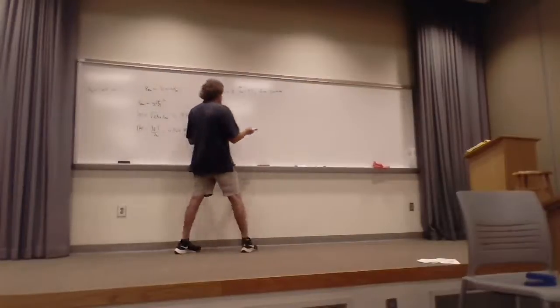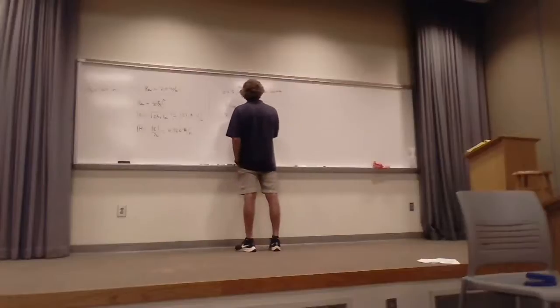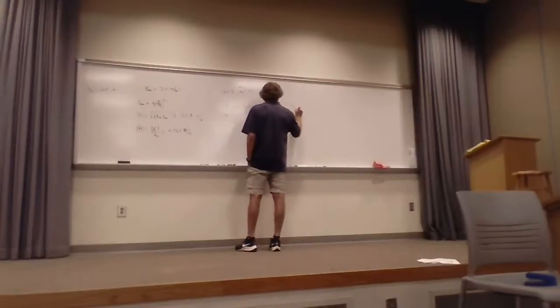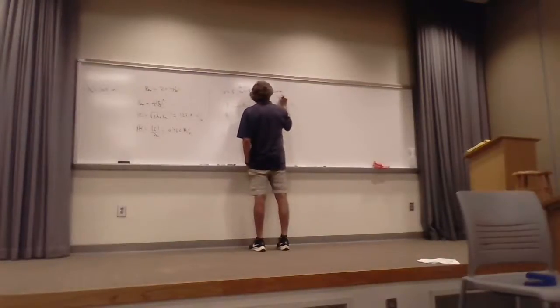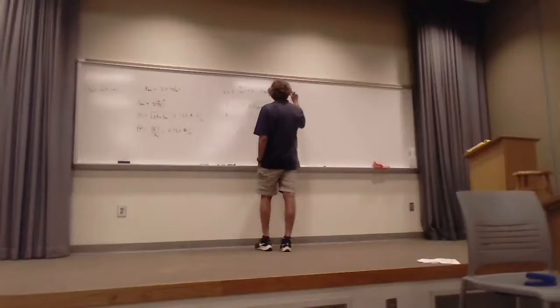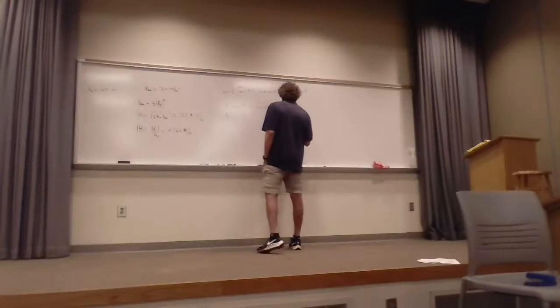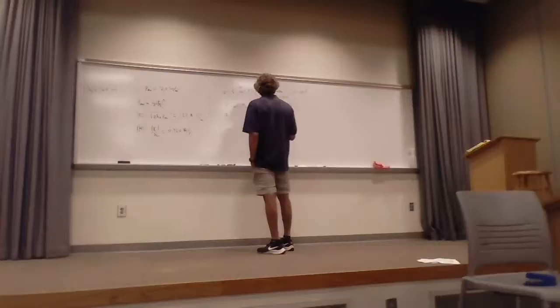For these, this is simply being familiar with the formulas. Gamma is the square root of J omega mu times sigma plus J omega epsilon. Here epsilon is epsilon naught times epsilon r, or 72 times epsilon naught. Omega is 2 pi times F, or 600 pi times 10 to the 6th.